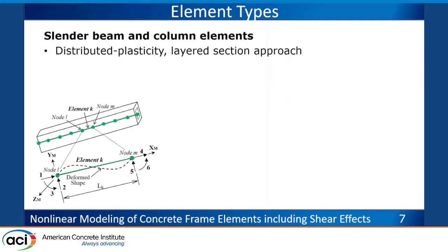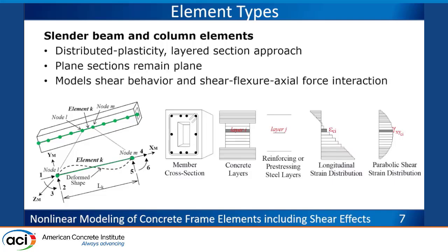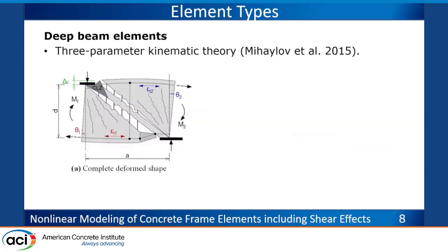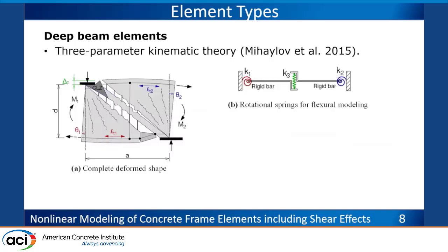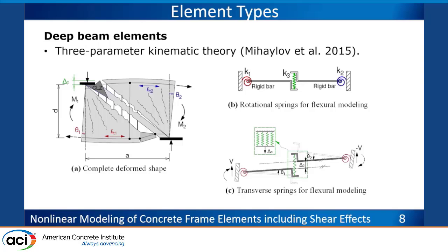So this is what I did in my PhD. It's a layered element based on distributed field theory. This is for only slender elements, considering shear, flexural, and axial force interaction. This is what we did with Dr. Mikhailov. It's a really powerful model. We implemented it fully, and I'm going to show some results soon. That's the other type of element.